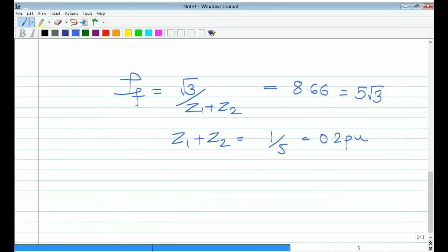The next is again from Alok Bhardwaj. If Pe is equal to 1 pu, delta is 30 degree, Pm2 is 0.5 pu, I think. Pm3 is 1.5 pu. Then for critical clearing angle, delta max is pi minus sine inverse of Pm by Pmax 3.